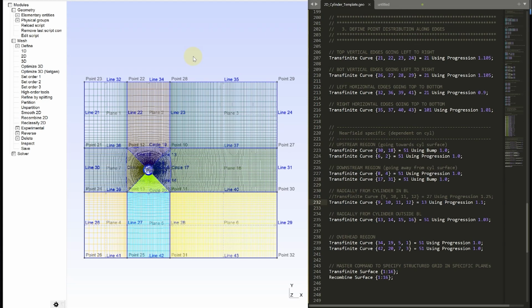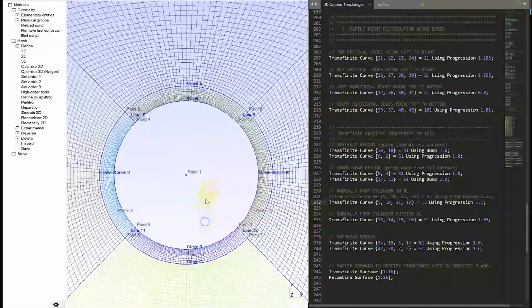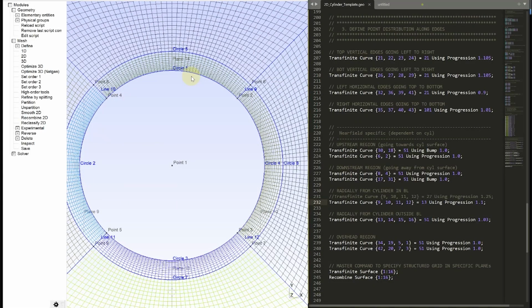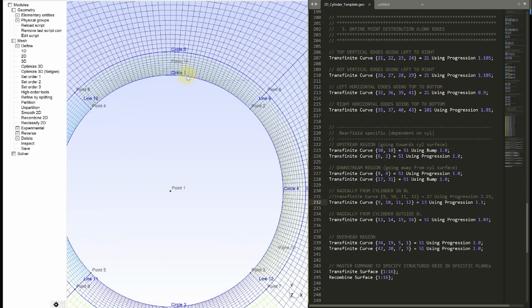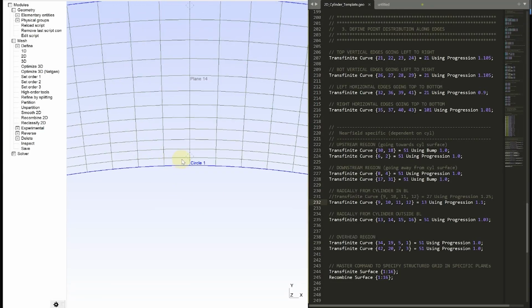There's another thing before we continue that I would like to draw your attention to: it is feasible and also very important for you to modify the mesh refinement level in different subregions of the computational domain. For example, if you want to get trustworthy results in your boundary layer region, or let's say predict accurate flow separation characteristics inside your boundary layer without using wall functions, you really need to make sure that your y plus value equals 1, which means that you really need to have a very small first cell height.